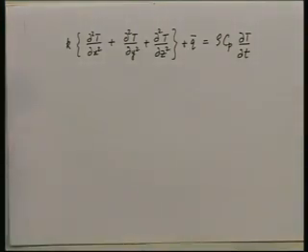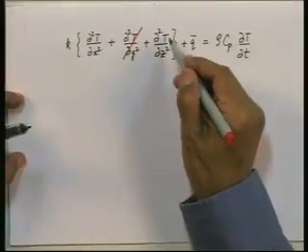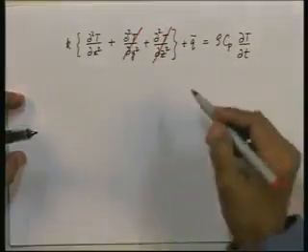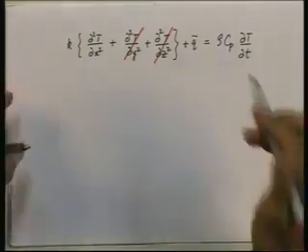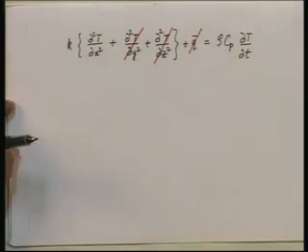In this case, temperature is only a function of x and time. So, d2T/dy squared will be 0, d2T/dz squared will be 0, and there is no heat generation in this case. Therefore, q bar will be 0.